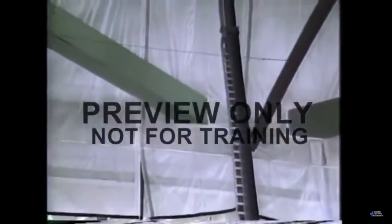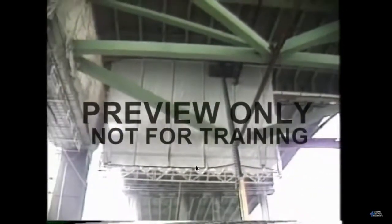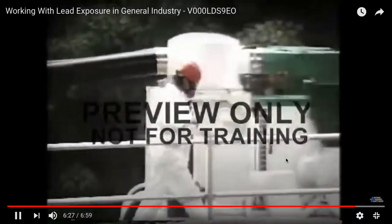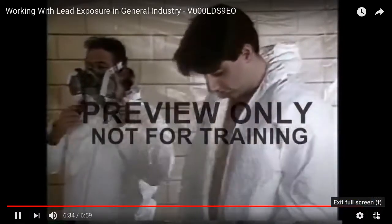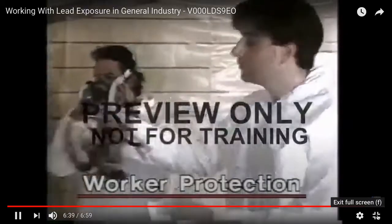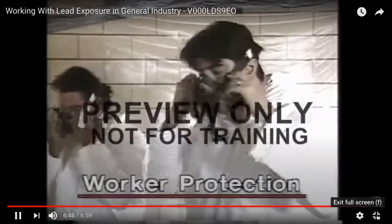As we said, in the construction industry, some tasks are very short in duration, with the potential for exposure to high concentrations of airborne lead. Unless properly protected, workers could easily be exposed to damaging lead levels before the results of the air monitoring tests come back from the lab. For this reason, the construction industry standard requires employers to provide workers with protection during this determination period. This comes in the form of protective clothing, respirators, and other personal protective equipment.